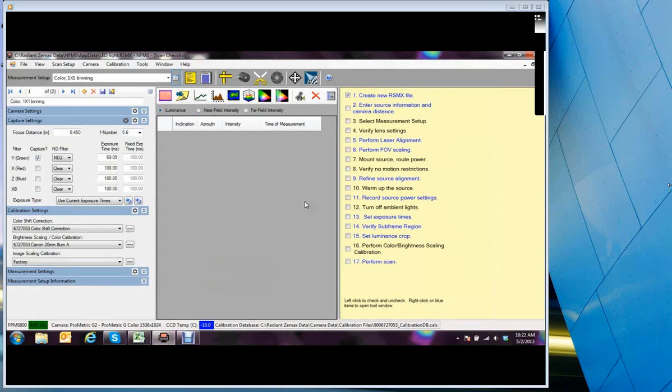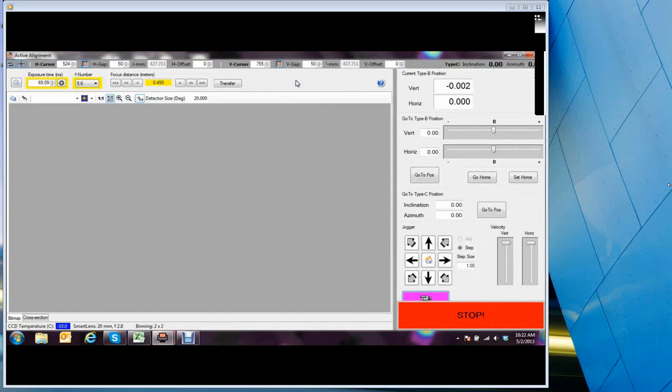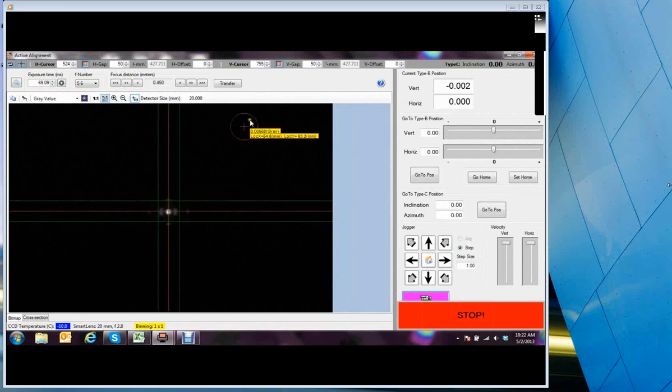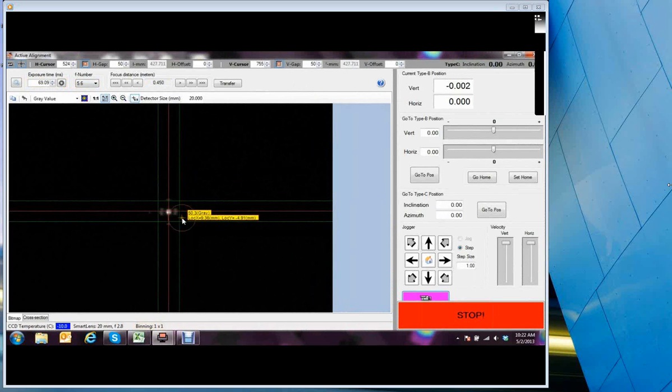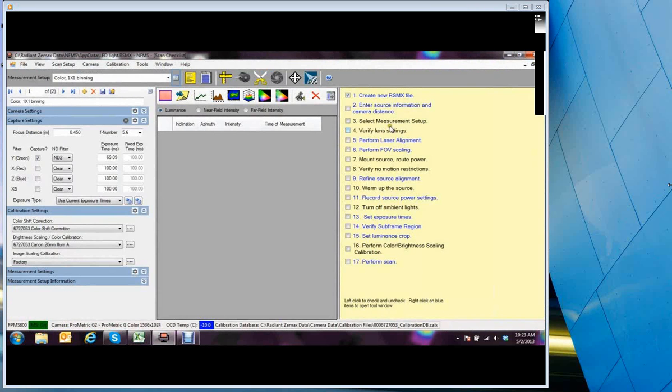Okay, so we have aligned our camera in front of the NFMS, making sure that the height of the camera and the offset from a known reference such as the wall have been verified. We've also optically aligned the system so that the camera's center optical axis and the center of rotation is well defined. We have also taken care to focus the camera and adjust the exposure time. So now we're ready to go down the checklist and verify that all of the software settings are correct.